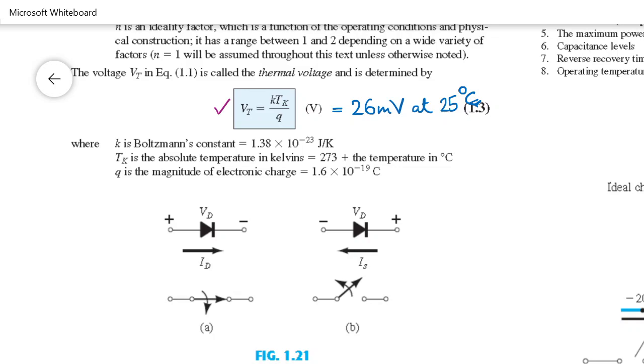Let us understand the forward bias. As you had learned, till a certain voltage, which is the barrier potential, there would not be any flow of current in the diode. Now you see here, till it is 0.7 volt, the current is 0. You can consider it 0. It rises a bit from a certain point before 0.7 volt, and it goes up. After 0.7 volt, it rises up very quickly.